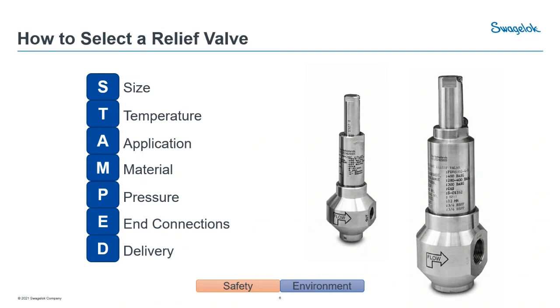And then some of the common issues that we see when we're talking about relief valves. One of those is that the valve is opening too often. One possible reason for that may be that your set relief pressure is too close to your normal operating pressure. In that case, you may need to set the relief valve pressure higher, but only as long as that spring is rated for it, and also only if that doesn't exceed your maximum allowable working pressure. So make sure that you're consulting all those things if you're having that issue.